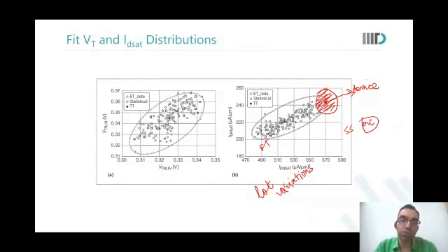And that is what you will do by means of running Monte Carlo simulations. This is also called Monte Carlo analysis, in which different variations are applied to different transistors. For example, the situation we just saw, where one PMOS is fast and the NMOS is slow, can appear even in a fast lot or a slow lot, where they were expected to both move in the same direction.